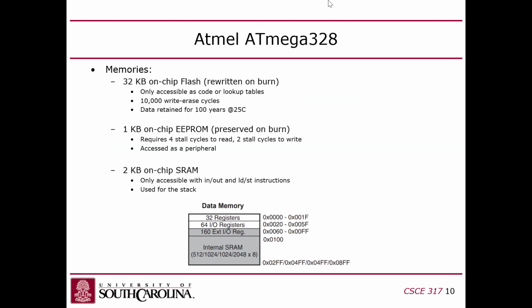All right, so this is also kind of unique because this ATmega architecture uses a Harvard architecture, which means that it has two separate address spaces. It doesn't have one common address space like most computers have. It has one memory that is just for your program, which is a flash memory. It's an on-chip flash memory though, which is kind of crazy, right? There's a flash in the processor, which is odd, right? I mean, there's no other processor that has that.